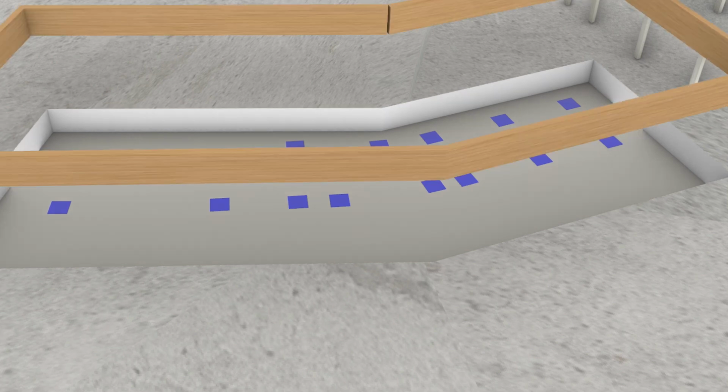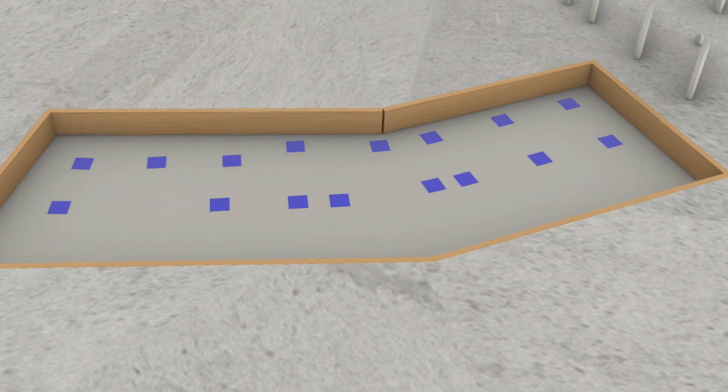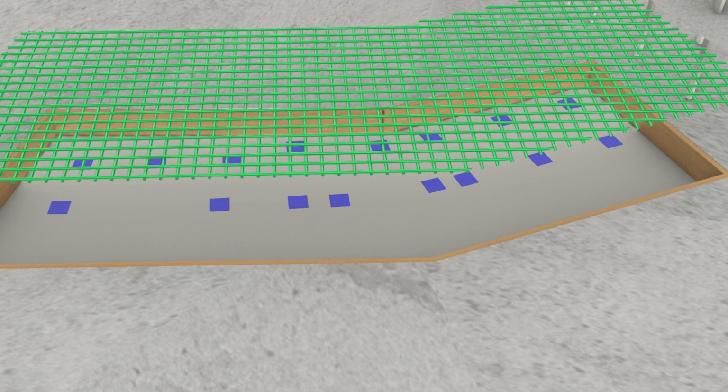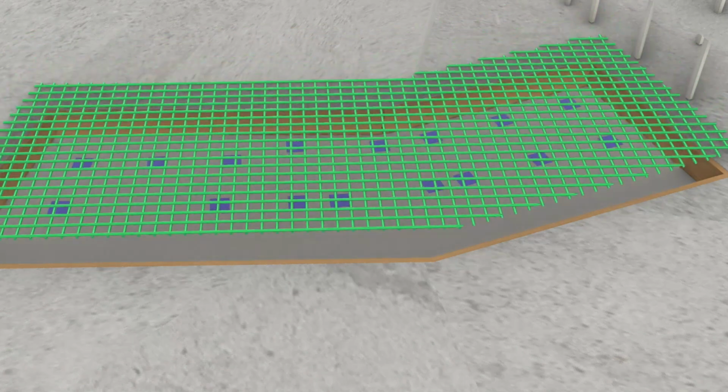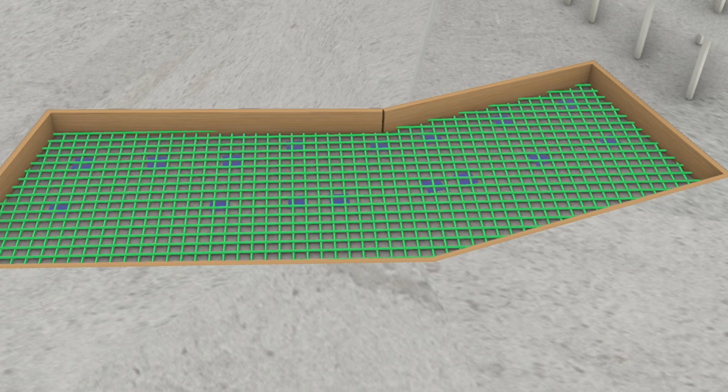The mat foundation was designed with a thickness of approximately 2.5 meters and a concrete strength of 8,500 psi, significantly higher than standard structures. Construction began with the placement of bottom rebar in a dense grid. Rebar diameter was around 60 mm, spaced at 300 mm intervals. Standard 12-meter long rebar segments were lap spliced over approximately 2.5 meters. This allowed stress to be transferred without cutting the bars, and the connections were tied with steel wire.